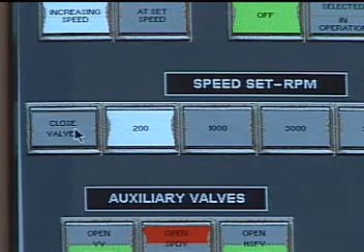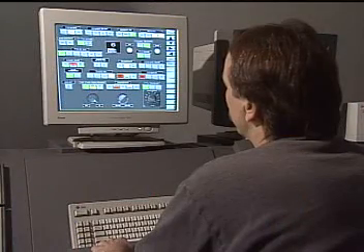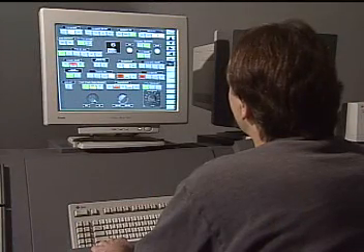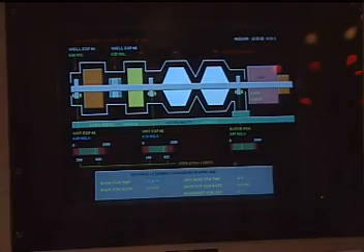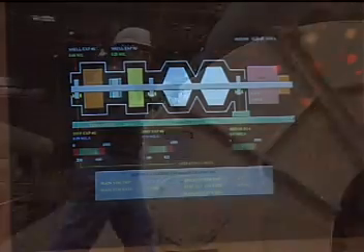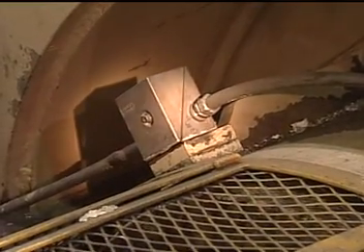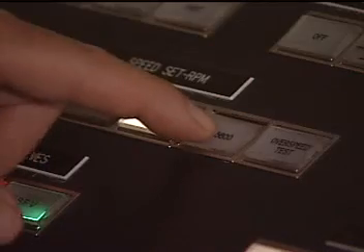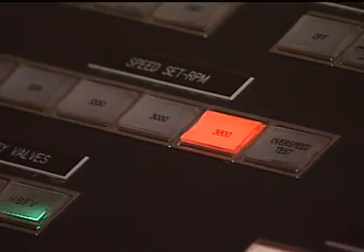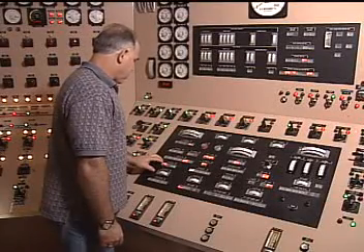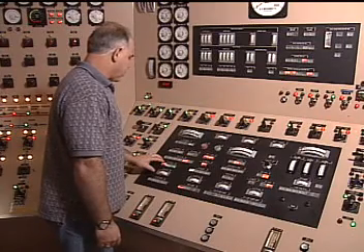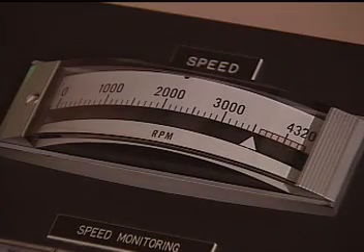Then the turbine valves are closed so that the turbine can spin freely while an inspection is performed. The turbine control instruments are checked for unusual readings, and the turbine is inspected for any unusual characteristics such as abnormal noise, excessive vibration, or unacceptable lubrication temperatures. If conditions are normal, the main steam stop bypass valves can be reopened, and shaft speed can be increased at the rate prescribed by plant procedures until the shaft is turning at rated speed.